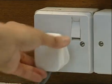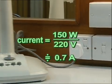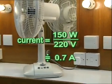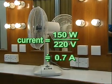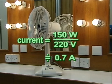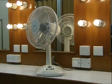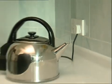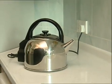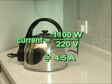For example, plug a fan of 150 watts to a socket of 220 volts. The current passing through the fan is equal to 150 watts divided by 220 volts, or approximately 0.7 ampere. Plug an electric kettle of 1000 watts to the socket. The current passing through the kettle is equal to 1000 watts divided by 220 volts, or approximately 4.5 amperes.